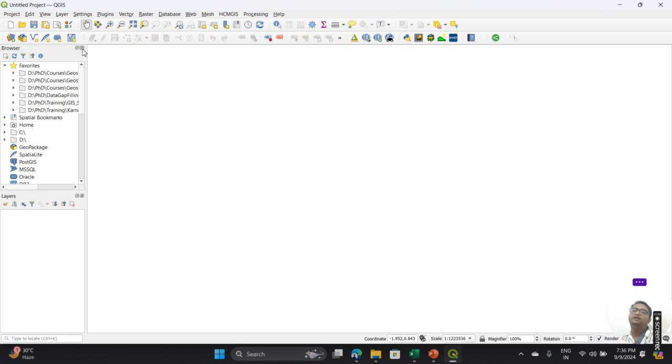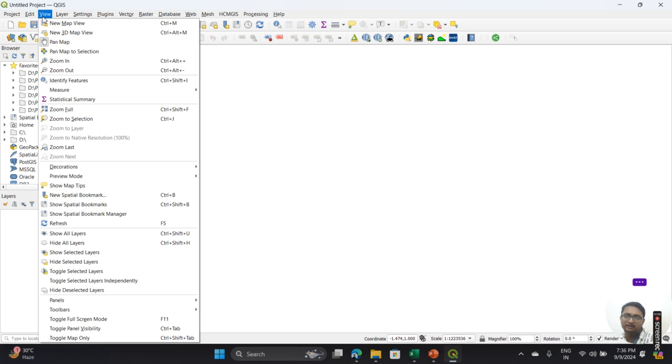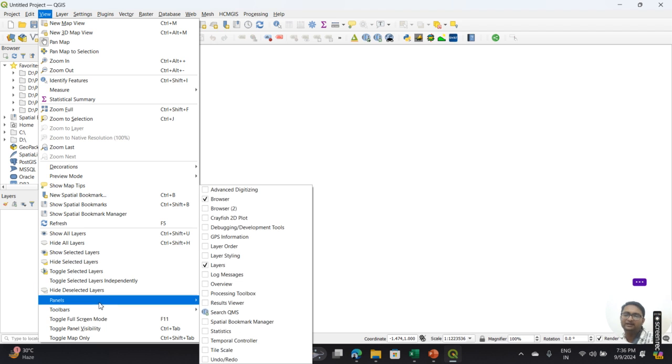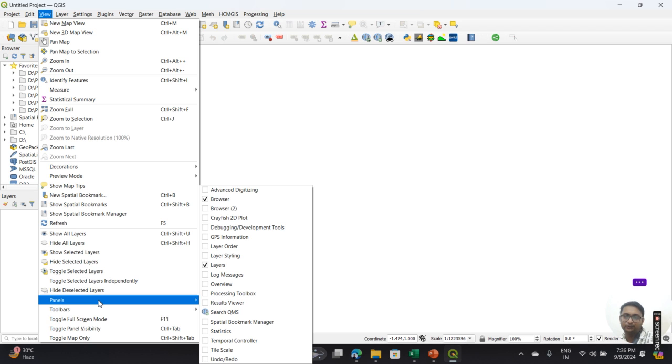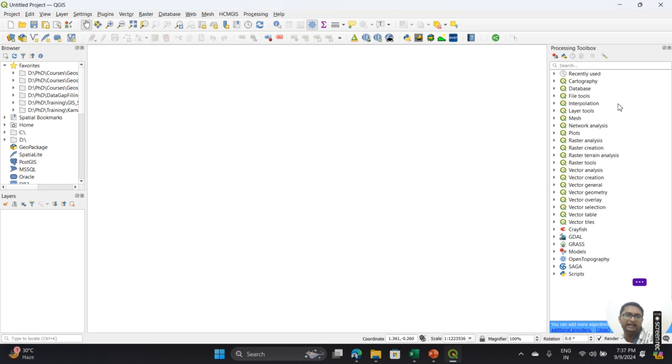Perhaps by mistake you have clicked on this close button. If it is not visible to you, first you have to think about what you want to do, because you do not need to learn this software as such, just see what you want to do. Right now it is not visible to me. So I will go to the View option, and if you explore, at the bottom you can see Panels and Toolbars. I can go to these panels, because those are the different panels, then go to this processing toolbox and just click on it. So it will add that processing toolbox.